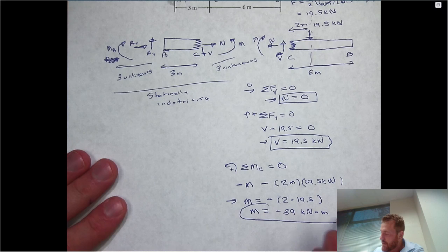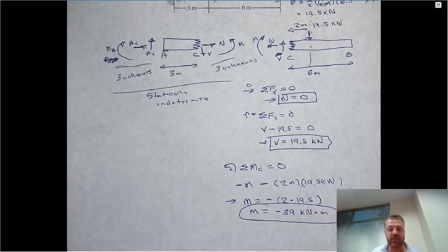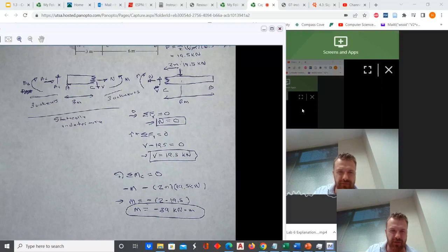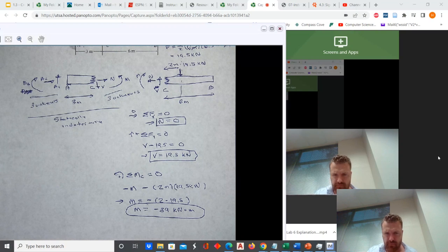So hopefully that makes sense to everyone of how you compute those three forces. Pretty much a review, that's very similar to the problem that we did last week, where we, in addition, were able to pass a section and get a statically determinate system that only involved the unknowns of the internal force system at the point where we're trying to solve. So what we're going to do now is transition into a technique of finding a graphical expression for the internal force systems over entire beams, and that's known as shear and bending moment diagrams.